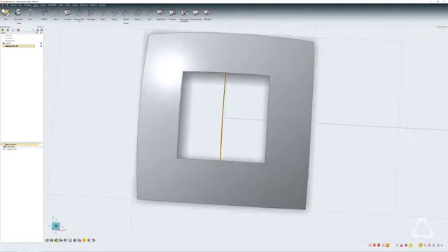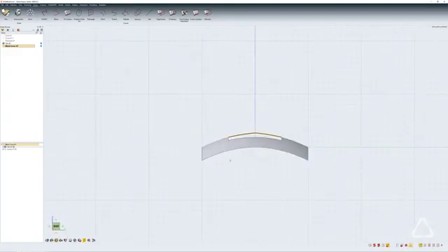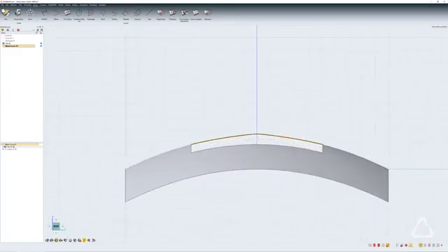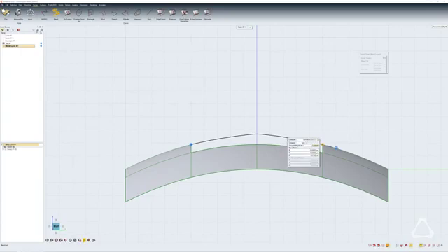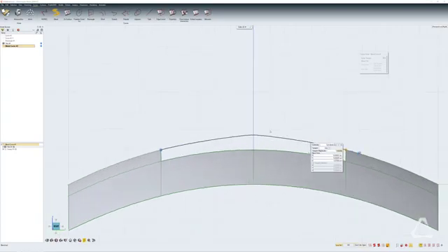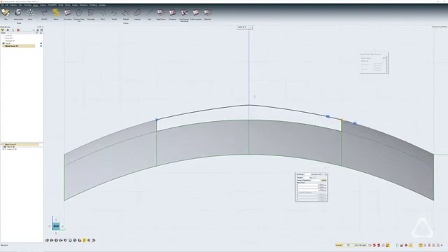If I go back to my right view, I would like to add a shape to the loft. By default there are only 2 points. You can change the shape of the blend curve by selecting the blend point, expanding the controls here, and changing the magnitude to a different value. So if I change it to 2, you can see that the curve is bizarre. The default is 1. In order to reduce this small peak that you're seeing at the middle, you want to reduce the magnitude of both the points. So I can select both points and give them a magnitude of 0.8 or 0.9